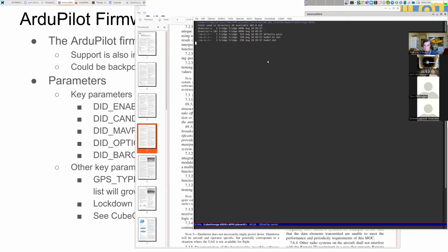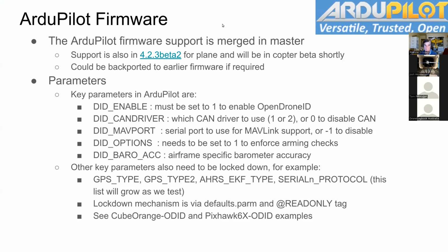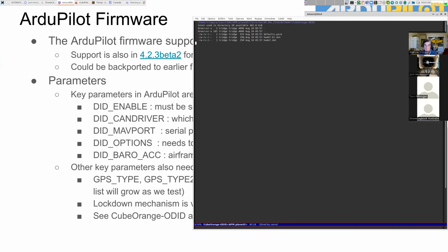Is there anything regarding private ranges? So not military ranges, being on a MOA. FRIAs. That would be a FRIA. If it's a FRIA, you can fly within the scope of the FRIA. But if it's not a FRIA, like let's say it's private property, like a cornfield that your friend owns, you would still be subject to remote ID because that cornfield is still under FAA jurisdiction.